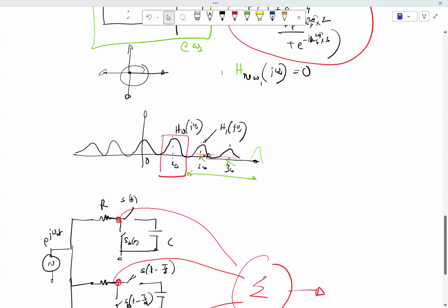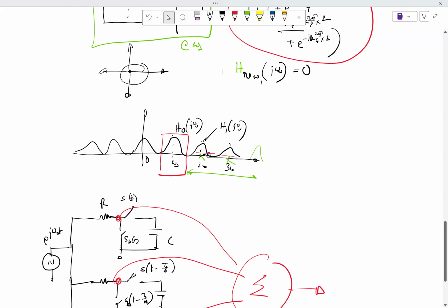Essentially we are searching for a good bandpass filter, right? A good LTI bandpass filter will have a flat in-band response and a sharp roll-off, and nothing should come after that. Here in this case, we don't have sharp roll-off.